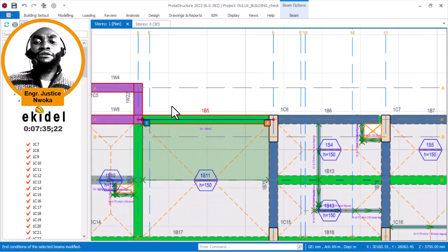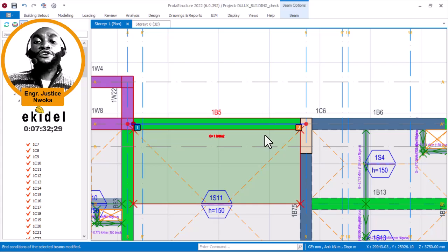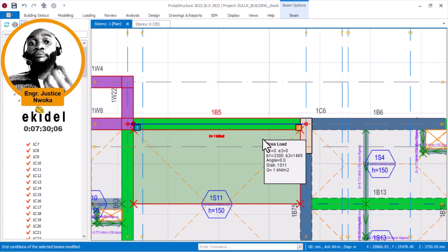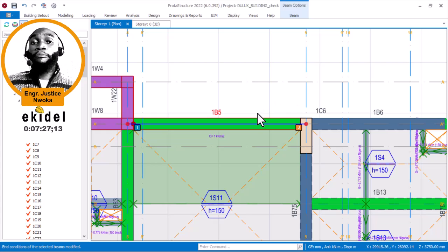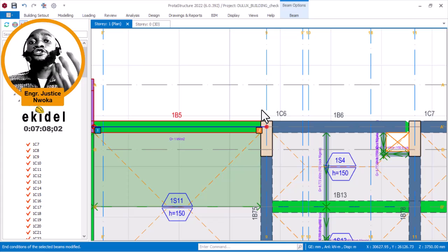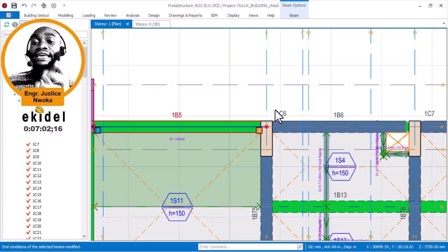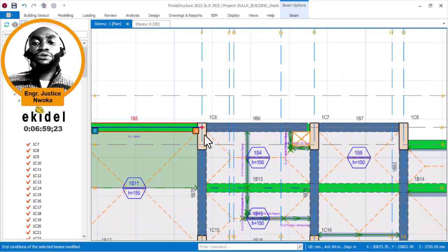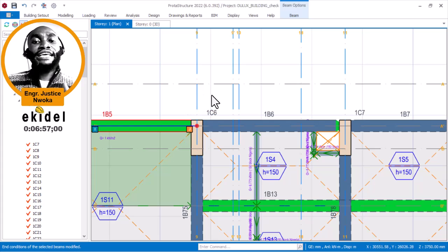So with that right now, this place from here to the point where the moment changes its direction from bottom moment to top moment, here can be 2Y16 and all that, which is the minimal reinforcement. Why here? Knowing that here had the hogging moment, here cannot be 2Y16, here can be 4Y16. So you are going to have additional reinforcement at the support here at the top. Okay, that's fine.